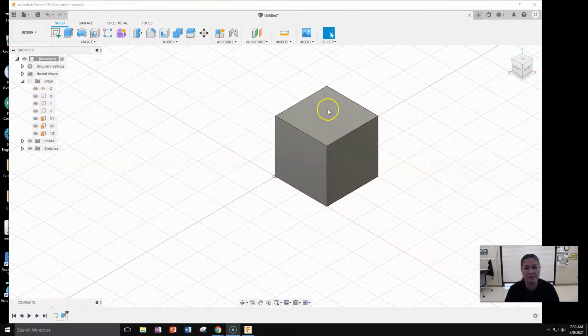Okay, and let's just add a new sketch. Let's go up to create a new sketch. It automatically closed the old one. You see how the sketch tab is gone up there, but you had it earlier. So that green check mark that I never hit, that's in there. So if you look in here, you'll see that's going to be that square that we made at the bottom. 2D sketch, that's the square. 3D model, that's the cube. Got to know the difference, right?